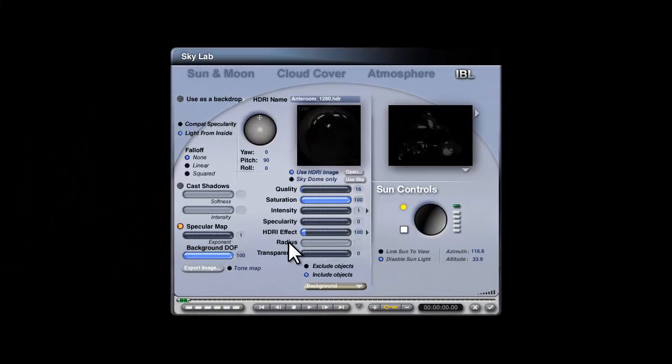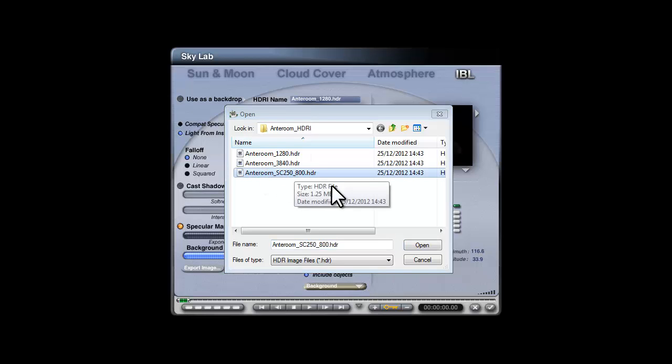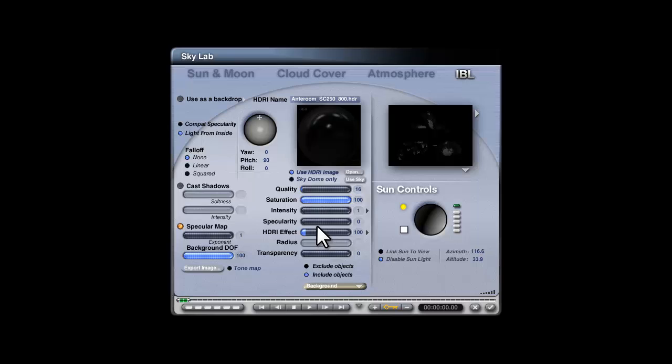Go back into Bryce now, and I'm going to open Horo's Specular Convolved version of this. So now we've got the Specular Convolved image. I'll bring the intensity up to 10, and we're still going to use obscure lighting in this, but I'm going to turn off True Ambience Optimization because it gets turned on again by default when we load this image in. Horo's done this in a different application, so it doesn't look as soft, but it is softer, so that will provide some effect of directional lighting, but it'll also do something to mitigate the noise for us.